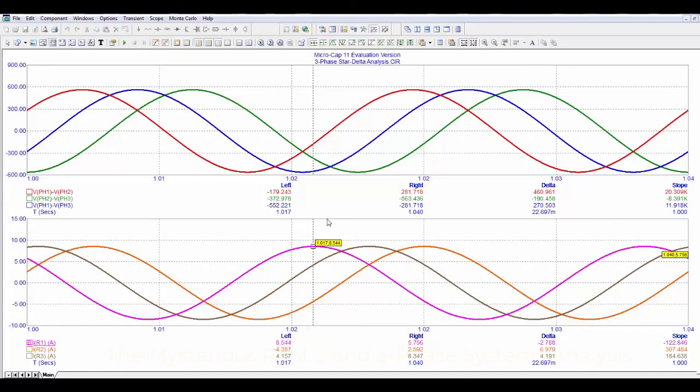If you then divide this peak voltage value here, 563.4 almost, by what the overall impedance would be, and the overall impedance is the square root of 20 squared plus XL squared. XL comes out to be 62.8, so impedance for that series combination of R and L is 65.9 ohms.